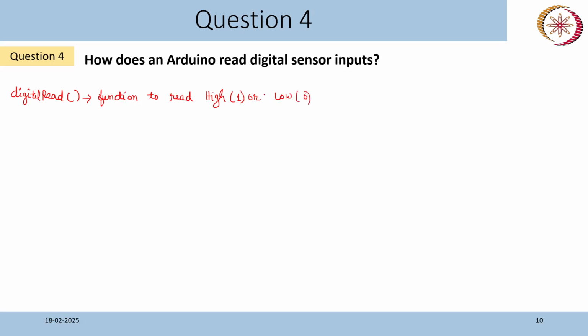So you will use digital read when you have an input pin from where you will get the data. Suppose you are interfacing a sensor, the sensor output is either high or low, and you are reading that data. It's not that you connect your actuator and use digital read. You can do that, but it does not mean anything. So you will use this with an input pin.